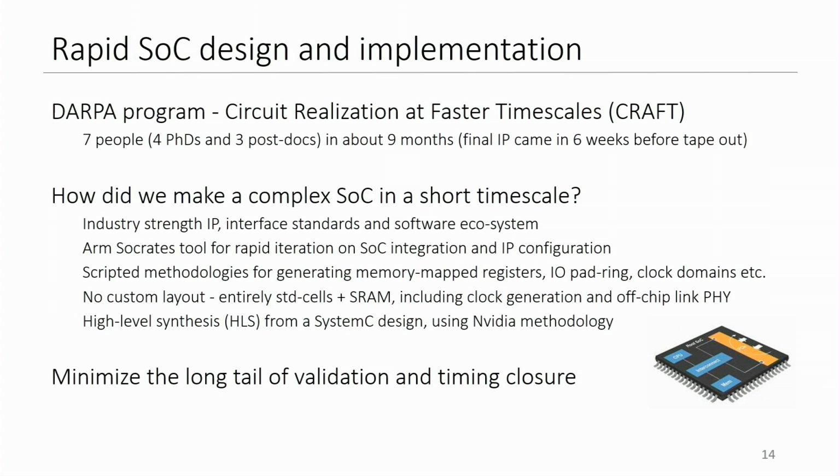We also reused some tooling and methodologies from previous chips at Harvard. So we have scripted methodologies for generating things like memory mapped registers, I/O pad rings, clock domains, all these kinds of things, pretty standard in industry. And then one interesting methodology choice is we didn't use any custom transistor layout at all.